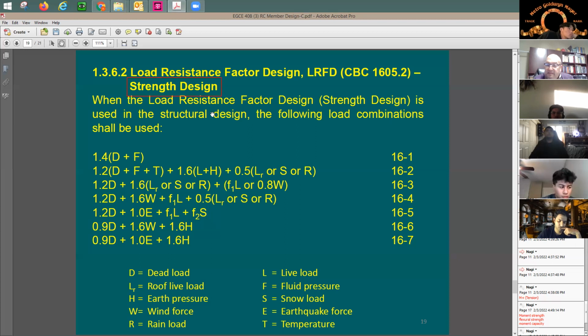I'm going to say here in the strength design, I have some uncertainties when it comes to the actual load that you're going to put there. This is the reason I'm going to have here load factors. So if you tell me here the dead load is going to be, let's say, 10 kips, I'm going to say, you know what? I'm not going to be using 10 kips. I'm going to add a little bit to it. I'm going to use here load factors. And how much increase are you talking about? I'm going to say when it comes only to dead load, it's going to be 1.4, which means 40% more in my design. You can call this safety if you want to, kind of a safety factor. But for us, we call it load factors.